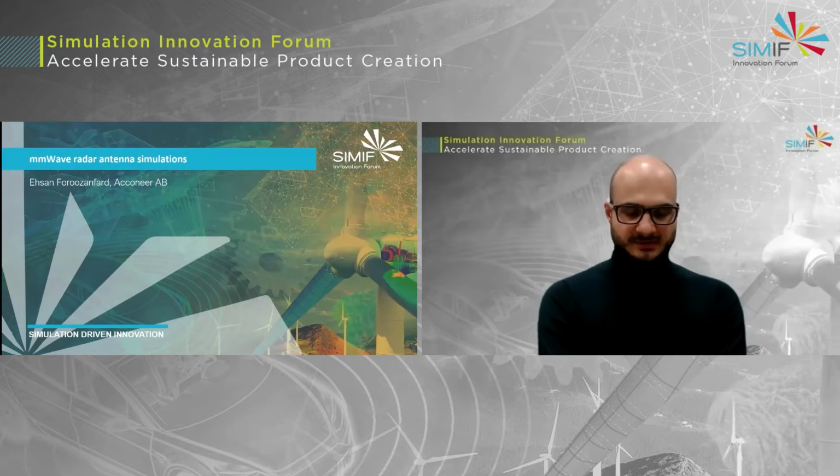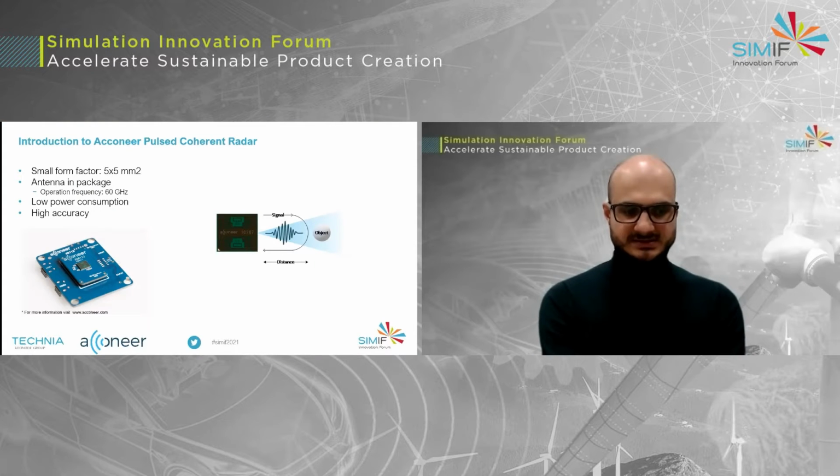So a little bit of introduction to the Acconeer pulse coherent radar. The radar system is based on the pulse coherent radar, which operates at 60 gigahertz frequency band, and the radar system delivers high precision and a low power consumption, and all the baseband, RF front end and the antenna is included in a small package by a form factor of 5 by 5 millimeter.